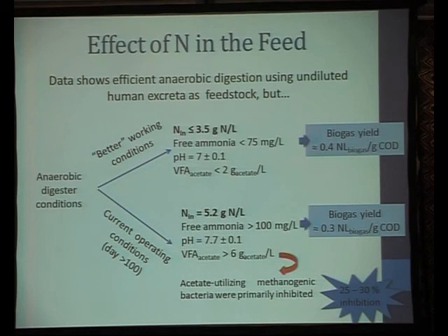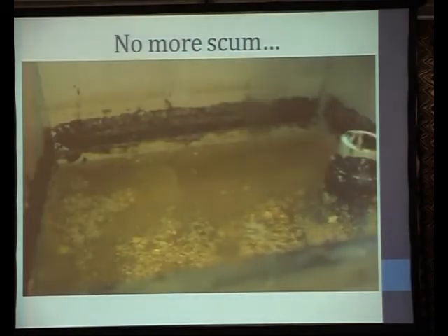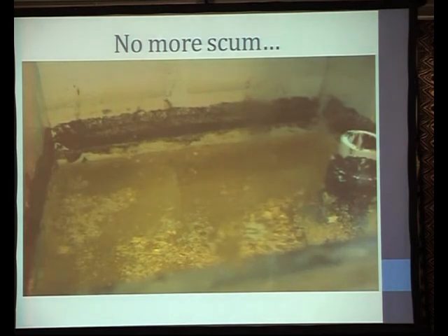Again, methanogenesis is a complex process with a number of different bacteria doing different transformations. Those methanogens here are affected, as indicated by increased acetate concentration. We also see some other interesting things happening at the same time. Remember that we had quite a bit of scum at the surface of the reactor. Now the scum has disappeared. Is it linked to those phenomena happening in the reactor? We don't know.